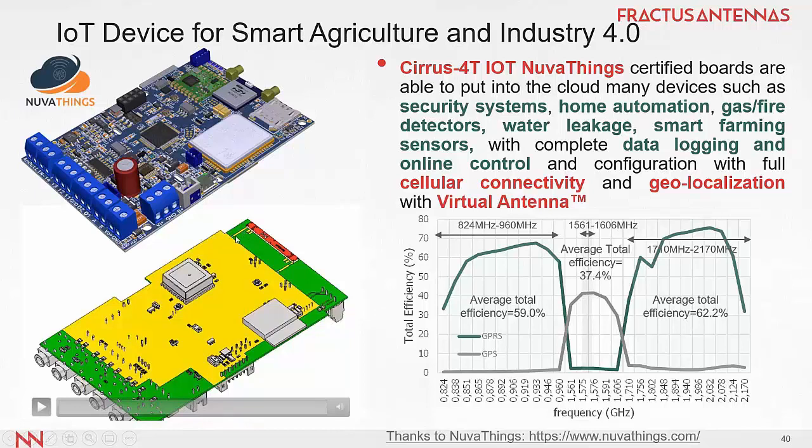So in this case, we are using this trio antenna with 2 ports. And in some products, we are already doing that with 3 ports. So one port can be handled for LTE, another port can handle the GNSS frequencies, and another port can handle Bluetooth frequency bands. So it's really a quite flexible antenna technology, not only for multiband, because this port here is multiband, but it's also multi-communication, because you have LTE plus other communication systems, GPS, and eventually we can put another port for operating Bluetooth.